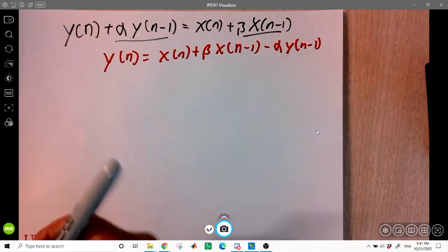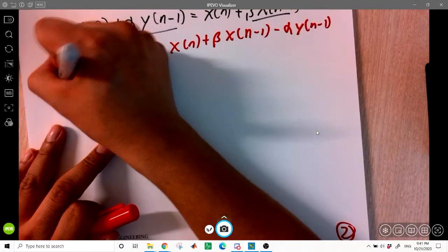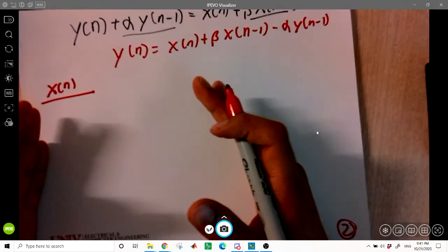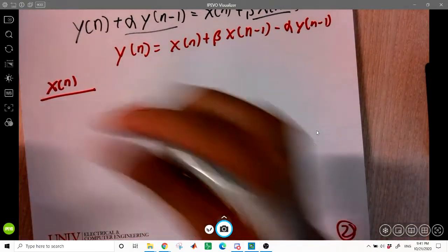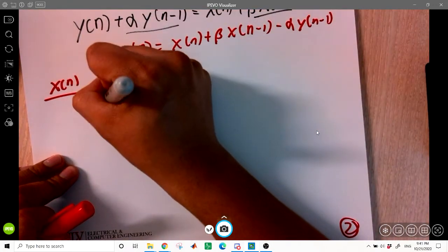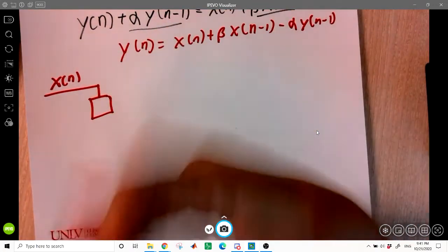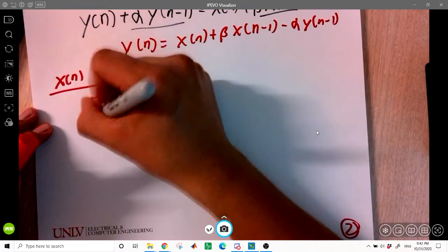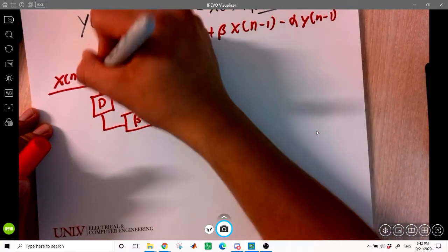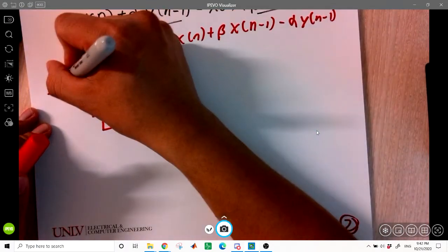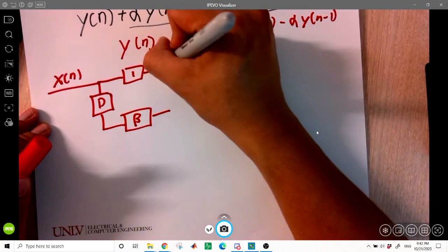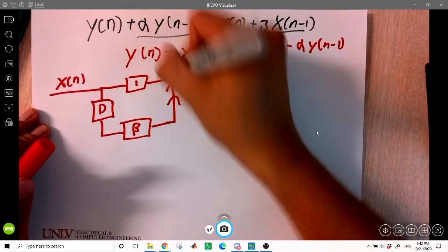Everyone should also be able to draw what we're about to do right now. Suppose we have our input, and we ask, how do we do this? We're going to do a direct form 1 block. This is the way you go with direct form blocks: first, you draw your wire, and then look for memory. Here's your memory, and then we design these memory blocks. So we have some delay, then we have some gain, and then we have a gain right here. This input goes directly into the output. Let's do this for clarity's sake. Plus, so let's draw our arrows.